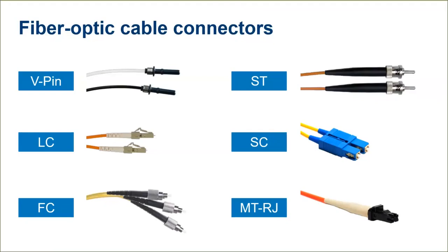Below that are the subscriber connectors, or SC, or standard connectors, and they are used for both multi and single-mode applications. Although they have a large installed base, they are beginning to lose popularity, at least in North America, due to the more favorable, more compact LC connector.